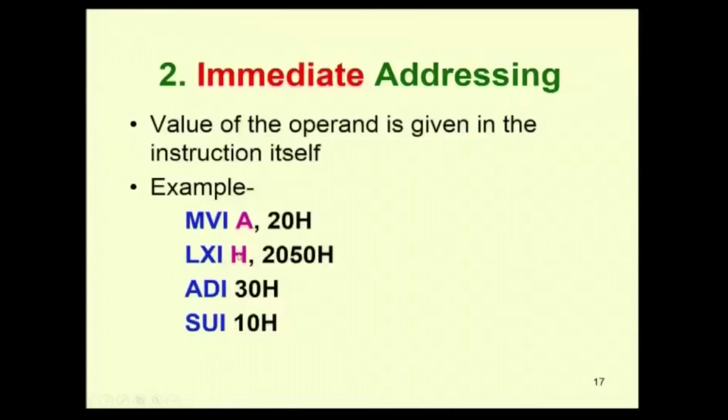Okay. So, H actually means H and L. So, this 16 bit data will be moved to H and L. We give the opcode for this, and this opcode is immediately followed by the 16 bit data that has to be moved.